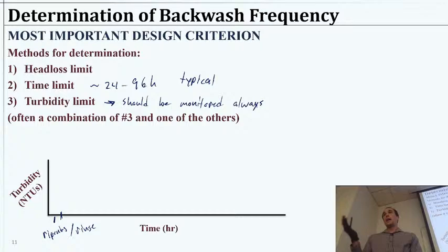The turbidity will actually be kind of high. There's particles escaping because everything was just shaken up. Even though we backwashed it for a little while, there's still some particles hanging out and not stuck and stable. So when we first start operating, the sand will be rearranging a little bit and we're going to get into a groove. But before then, we're going to have some turbidity, but it'll decrease up until the point where we're ready to operate.